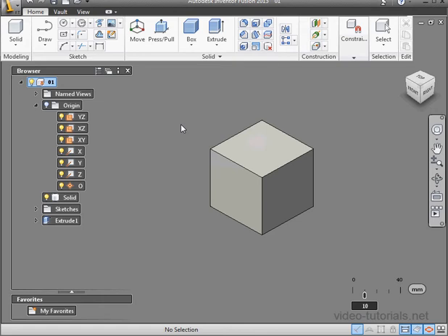So if we keep this analogy going, we could say that a hollow cube is kind of built from surfaces. Technically, foil is not a surface since it still has some thickness, even if it's very thin. What's different about a surface is that it has zero thickness. It has no mass. You are not able to assign materials to surfaces. When we create a solid, like you see in my graphic area, we've created 6 surfaces. If we stitch them together to create an enclosed volume, it becomes a solid.